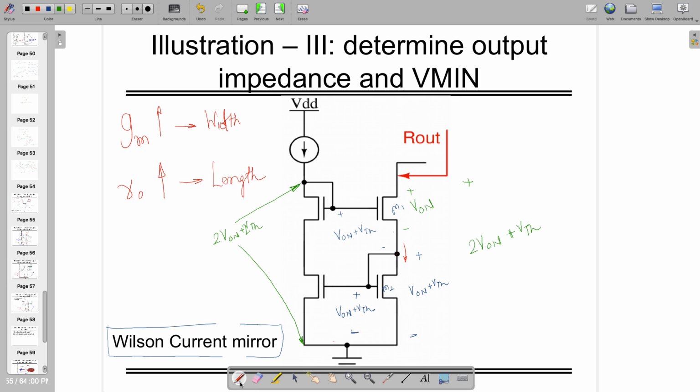So in this way, it's comparable to the Cascode, but it's not as good as the regular one where we used to have only V on as the minimum voltage requirement. So as per the feedback theory, it is the winning one, and this is giving you the stable current we want with the minimum error. But as per the evaluation criteria, it is not giving you better results.